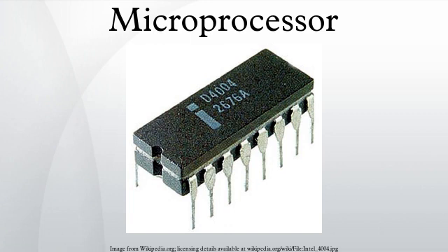Starting with the successor to the 80386, the 80486, the FPU was integrated with the control unit, MMU, and integer ALU in a pipeline design on a single chip, or the FPU was eliminated entirely. An ostensible coprocessor for the 80486SX, the 80487 was actually a complete 80486DX that disabled and replaced the coprocessorless 80486SX that it was installed to upgrade.